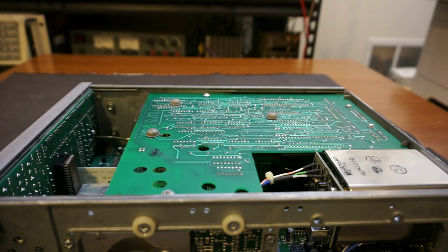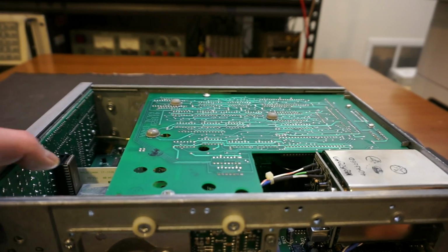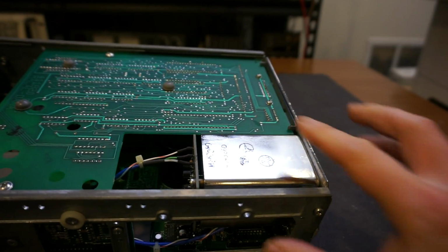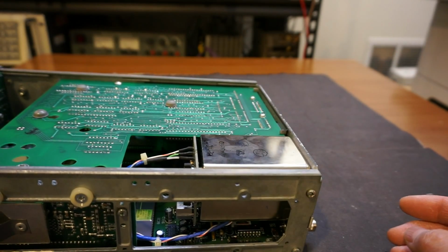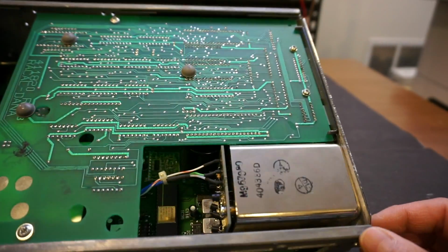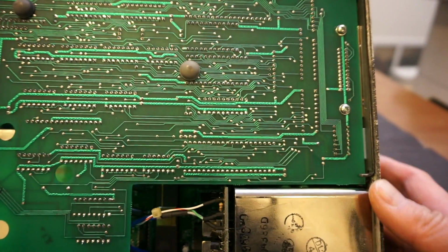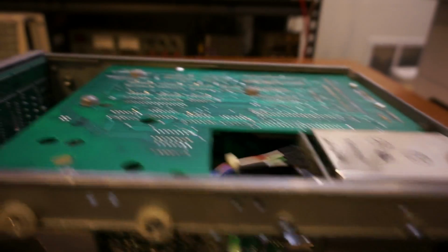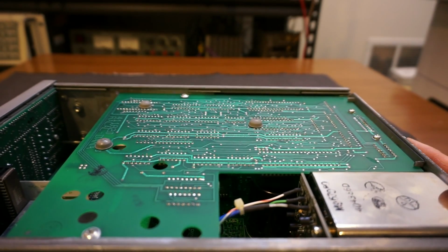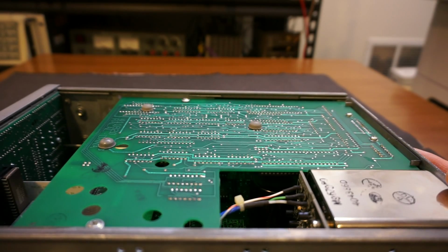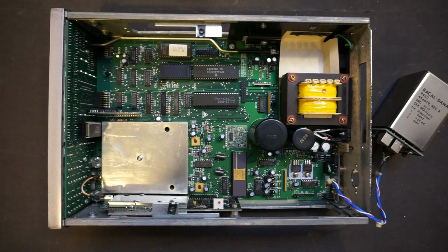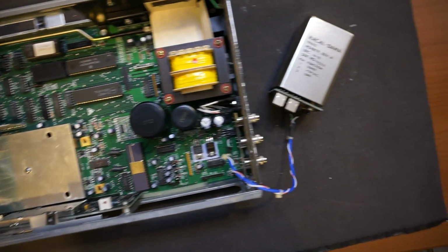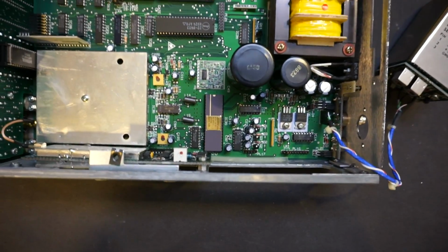And here I just opened it up, and surprisingly, this one actually has an ovenized oscillator as well. So as you can see here, this one is actually the ovenized oscillator. So now I think I need to take it further apart a little bit more to reveal the actual circuit underneath, because this top board is only for the GPIB, which we're not interested in for this repair. We have to take it out and see what is going on underneath. And I just removed the GPIB board, and also I removed this ovenized oscillator so that we have more space here to see what is going on.